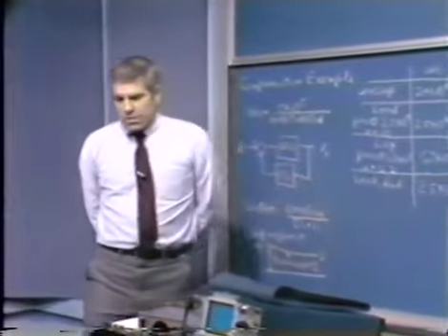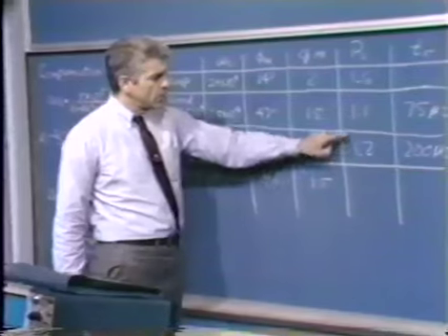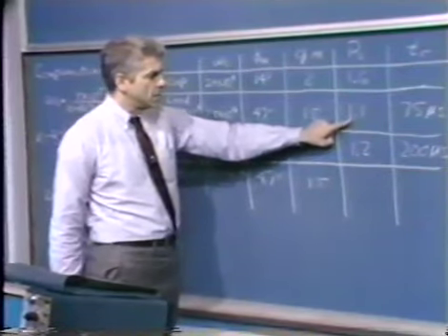Well, there's one apparent discrepancy that I'd like to spend just a little bit of time talking about. We had said that for systems with corresponding amounts of phase margin, the speed of response should scale just about directly with the crossover frequency. Furthermore, there should be a very nearly one-to-one correspondence between phase margin and any other measures of relative stability. The unfortunate part here is that we find out that in the lag compensated system we get a little bit more overshoot than we do with a lead compensated system.